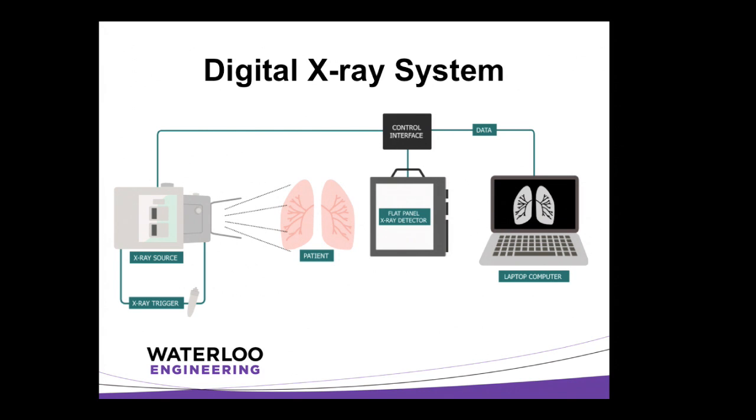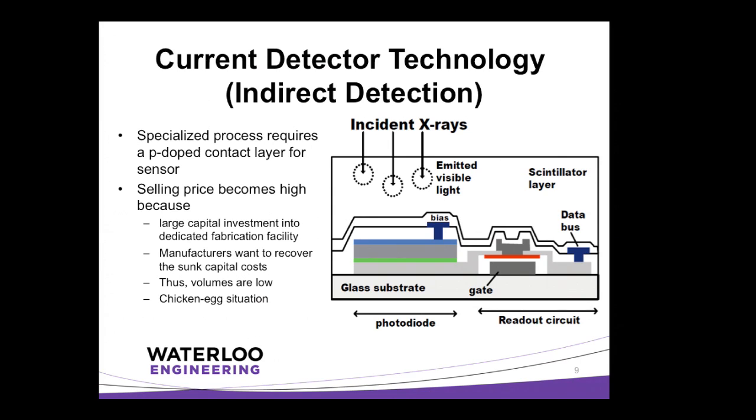Now let's get into a little bit more detail as to what's actually happening inside the detector, right? So when you look inside the detector, I've taken a cross-section of the X-ray imager. Okay, so this is where we get a little bit technical. What you have here are two basic devices at each pixel. It's a pixelated device, much like your digital camera. You hear 10 megapixel, 18 megapixel camera. Well, digital X-ray images are just like that, 9 megapixel, 12 megapixel, and so on and so forth.